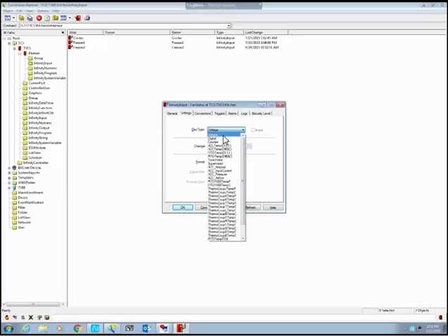If you have a humidity sensor or there's some other things that give you a 0 to 10 volt signal or 0 to 5 volt signal. CO2 sensors, CO sensors will do that. They would be voltages.